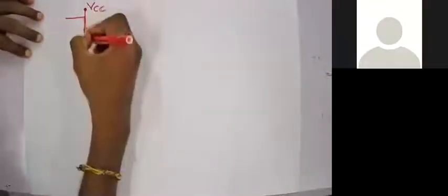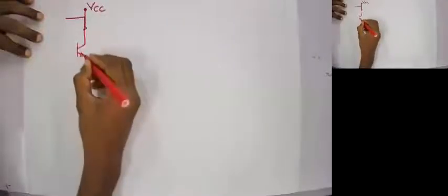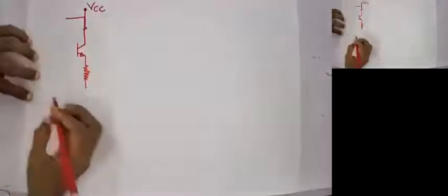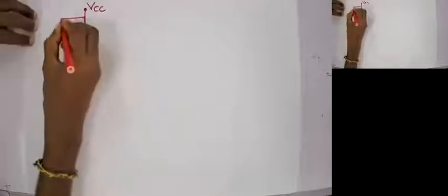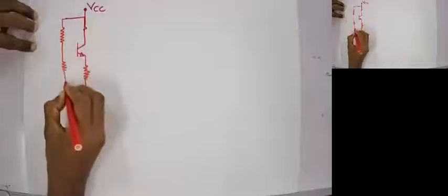So yeah, sorry, that will be. So there is no RC, right? So this is an NPN transistor. Here we have our RL, which is grounded, and then we have a potential divider for biasing the transistor.